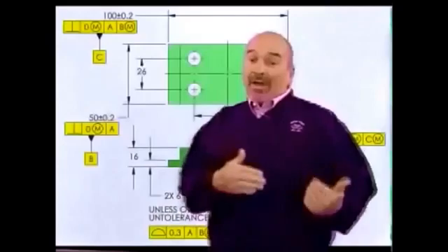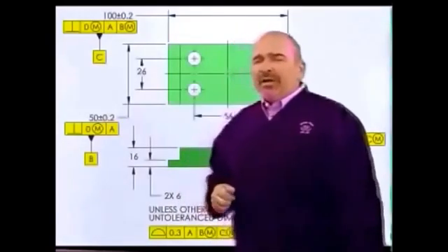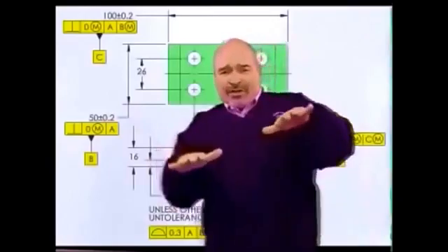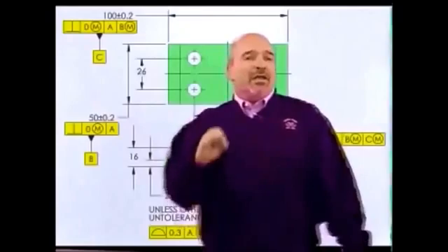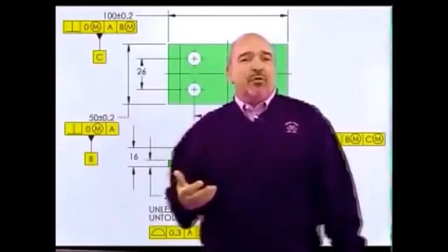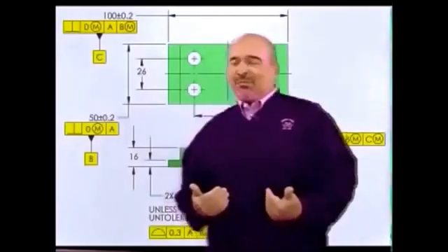Well, if we look at the Y14.5 standard, it says you pick the optimum one. The math standard, Y14.5.1, clears things up a little bit. It says, yes, there is an infinite number of planes there. They're called the candidate datum set. And you are allowed as an inspector to pick the one that will bring the part into tolerance.